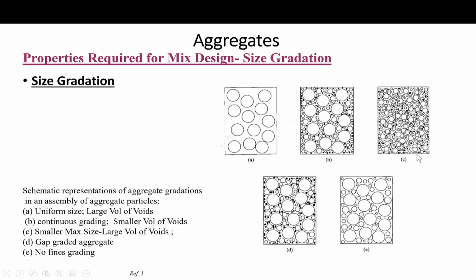So regarding the maximum size aggregate to be used, first, the aggregates have to be well graded, as we will look at in later lectures, in order to end up with the least possible voids between the aggregates, of course, while maintaining other requirements in mind.